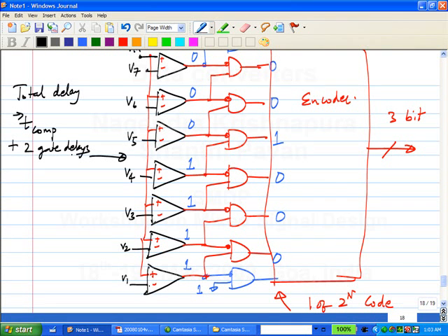And then you look at the outputs of each of these 7 guys and figure out in which bin the answer lies, because you will be able to figure out where this transition from all the ones to all zeros is occurring. So this massive parallelism is what is responsible for the high speed. It is also responsible for hardware complexity, because you are replicating this stuff many times.